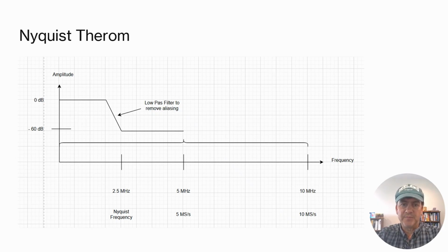In the case of an FM software-defined radio, we start with a 160 MHz sample rate, but we are only interested in a single FM broadcast channel. An FM broadcast channel occupies about 200 kHz of bandwidth. To preserve all the information in that channel, Nyquist tells us we need a sampling rate of at least 400 kilosamples per second. This is why decimation filtering is so powerful. It lets us safely reduce the sample rate from 160 MHz down to a few hundred kilohertz while retaining all the information we care about.